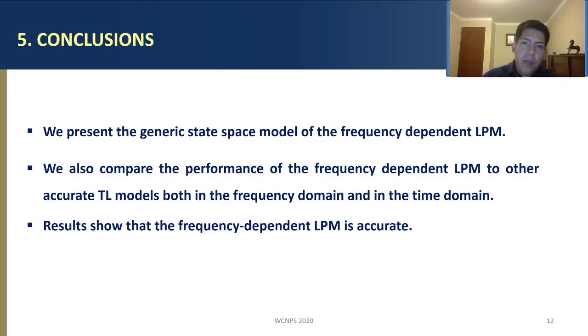We also compared the performance of the frequency-dependent lumped parameter model to other accurate time-domain transmission line models, and also with the analytical solution of the transmission line. We made the comparisons both in the frequency domain and in the time domain. Results show that the frequency-dependent lumped parameter model is accurate and can be used for the accurate simulation of transmission lines.